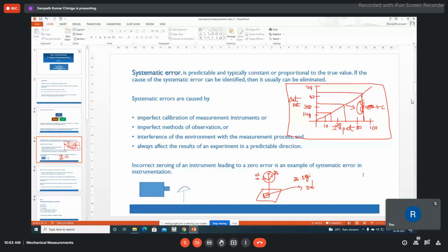That is what we call a calibration system, and it is very, very important whenever you are doing an experiment as a PG student or a PhD student in your doctoral studies. First thing for any experiment, even for a thermocouple you use for measuring temperatures, for example over the surface of a plate: to make sure that your thermocouple is giving a correct value, you use a hot water bath, wherein the temperature is controlled properly by a heater, and therefore the temperature of the hot water is measured properly.